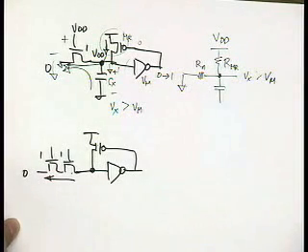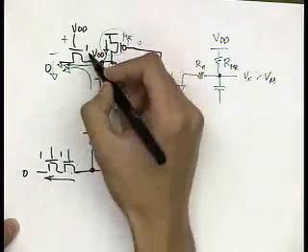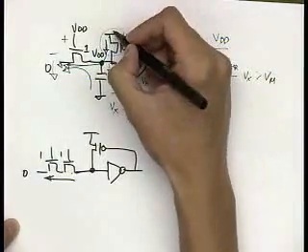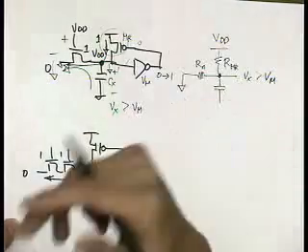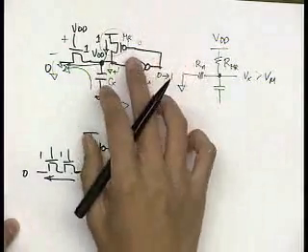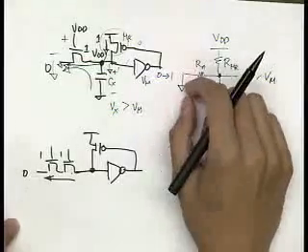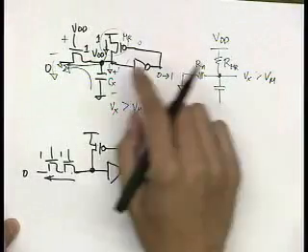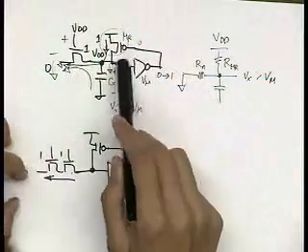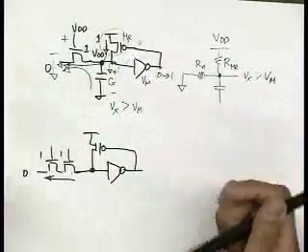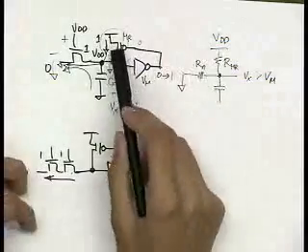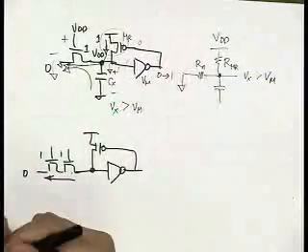Okay, and as we see here, if this were a 1, this would probably be approximately a 1. But remember, this is a PMOS, right? So it has approximately half the driving strength of an NMOS. Normally, it really depends on the technology you're using. Some people say you can use 1/4 the driving strength, increase the length by 4, and so on. But you have to figure it out depending on your technology and depending on your models.